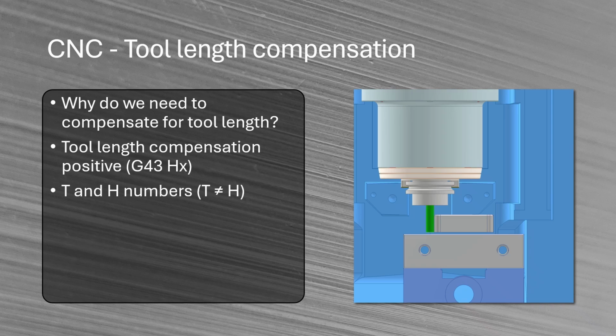But the reason that we don't for our machine is that there are only 10 available tool spots in the machine, and it cannot store any more T numbers, but it can have up to 200 H numbers. So for that reason, all the H numbers that are permanent, that are always saved on the machine, are above 10. So they start at 11 basically and then go up.